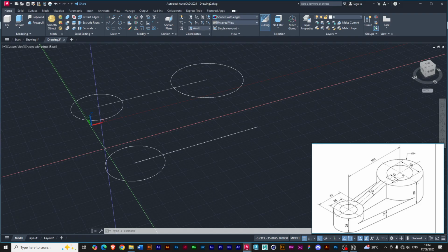42, right? Okay. Then pick the line tool. We want to get the center of the circle, so here. Then we want auto mode because right now this line isn't straight. So this is auto mode. Click here, then we type 100, enter twice to give us the length. Okay, this is where the problem is.